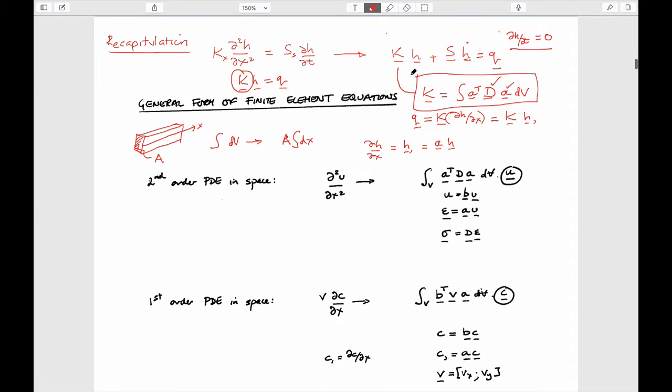discussion last time, or maybe a week ago today, to talk about the fact that this expression we have here is exactly the expression that represents a second-order PDE. And of course it follows exactly because this is a second-order PDE that we're representing. So whether we're looking at displacement gradients for stress-strain problems, or concentration gradients for Fickian diffusion problems, or pressure gradients or head gradients that drive flow in groundwater flow equations, this expression will be exactly the same. And all that will change is the individual components that relate to this.